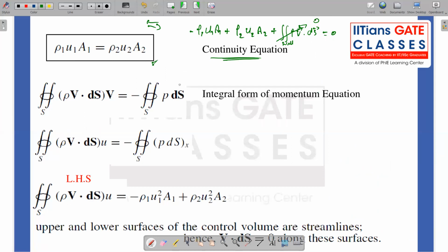Okay. Now we are going to analyze the momentum equation, and we have to note that the momentum equation is a vector equation. It is not a scalar equation. So I have components of velocities along which I have to divide my equation. Considering it's a steady flow, the steady part, dou by dou t of the volume integral, vanishes because of the steady assumption.